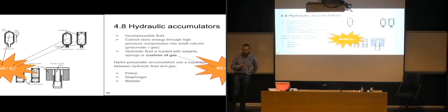But one thing is very important when we are using cushions of gas in them. We can't use air and we can't use oxygen inside it. So preferably we use nitrogen in them. That's the most commonly used gas. And of course the air and oxygen has to do with this fire triangle. We don't want to give the hydraulic system the ability of having both heat, fuel in the shape of hydraulic fluid, and oxygen. So we are basically just denying the system one of the parts of the fire triangle.